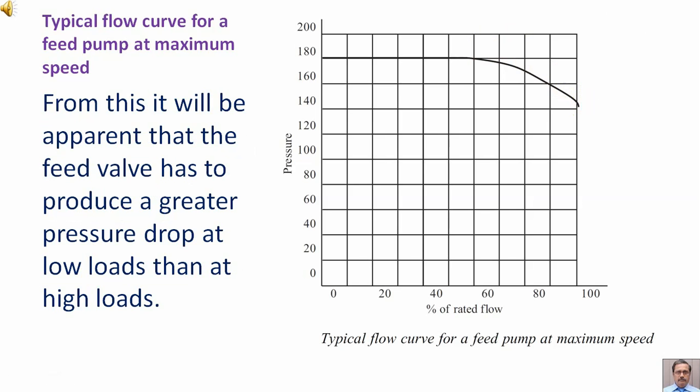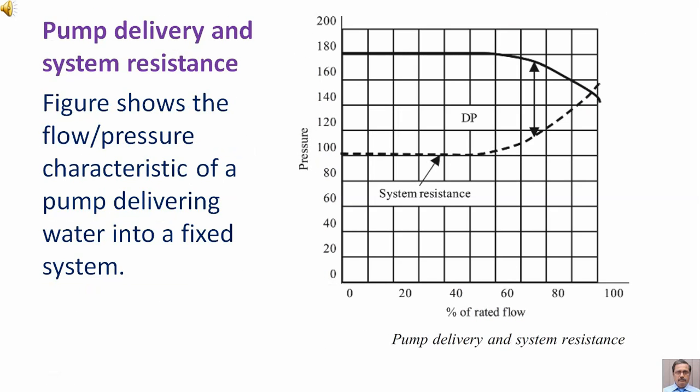From this, it will be apparent that the feed valve has to produce a greater pressure drop at low loads than at high loads. Pump delivery and system resistance.